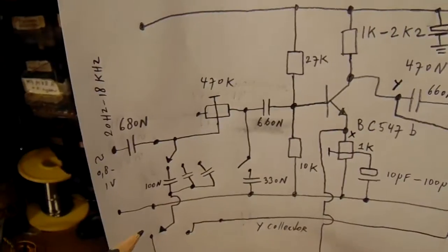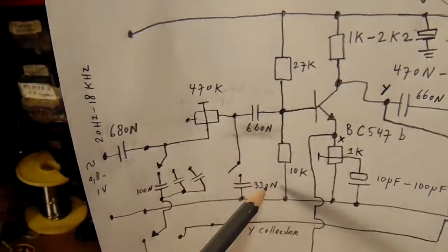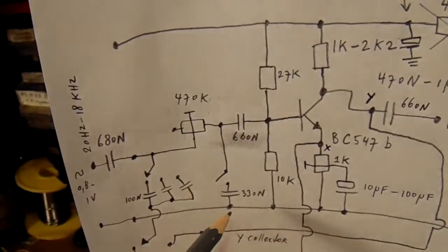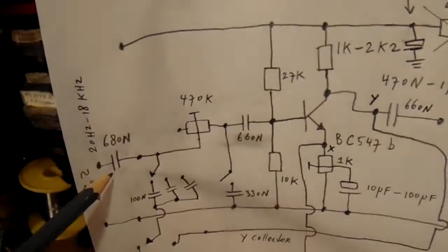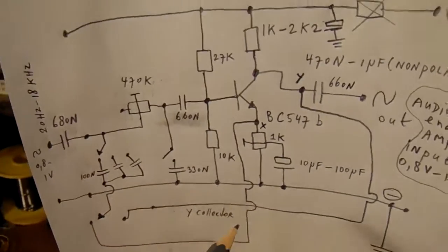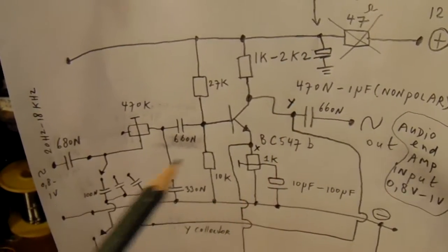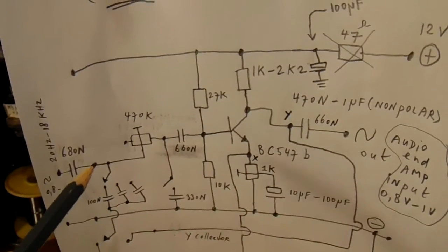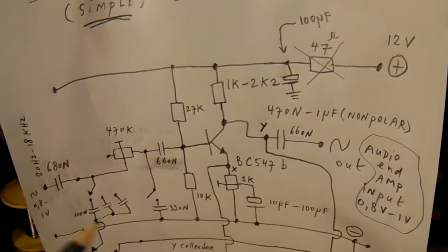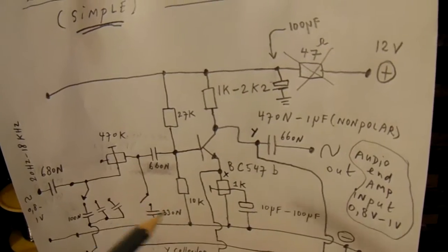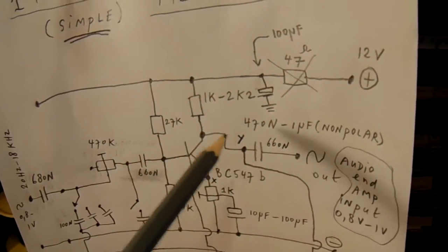But now we're going to make another connection. While we have the cap here where all the high frequencies are damped, we make a new connection from the input of the circuit, via a cap to the collector, and that means that apart from the audio signal directly traveling to the output, another part is amplified, the lower part, because here we cut off all high frequencies, the lower part is also amplified.